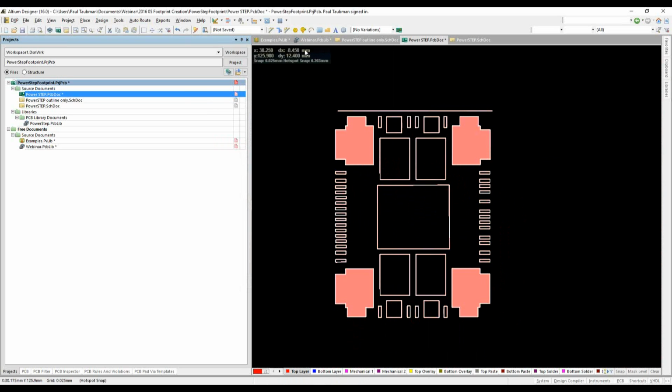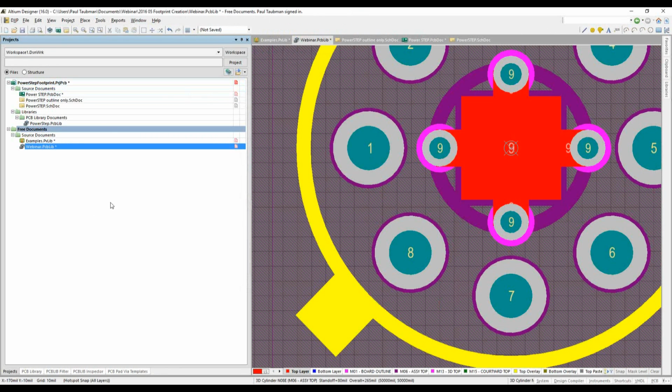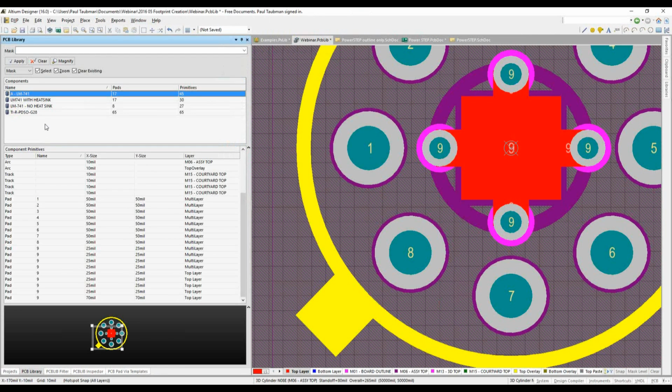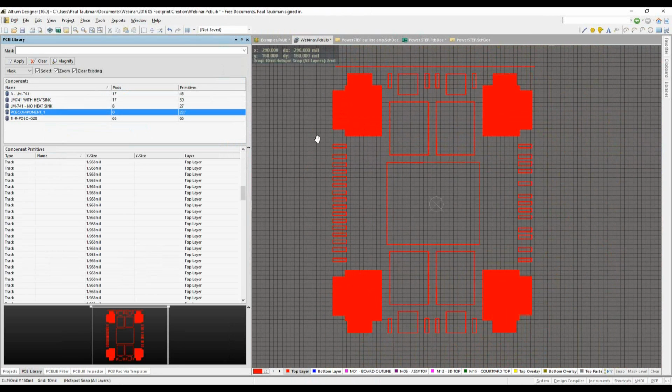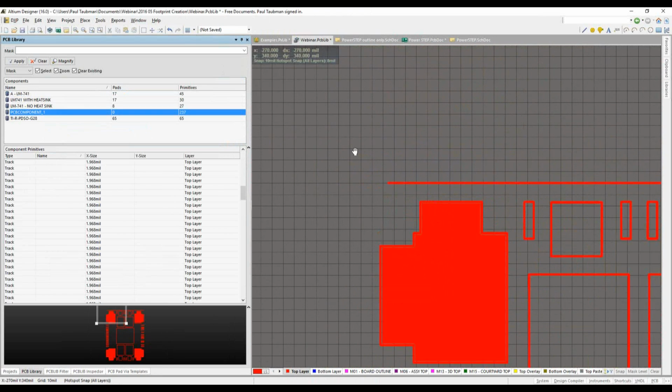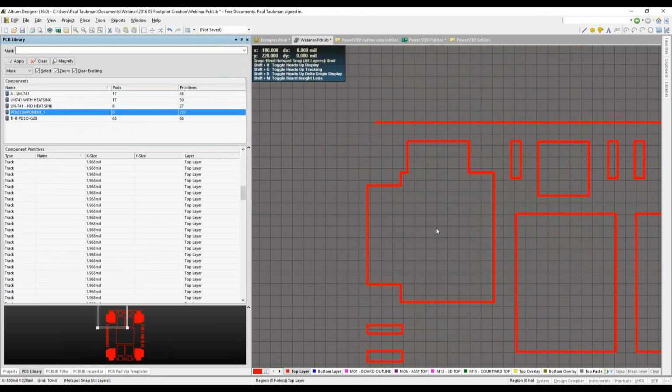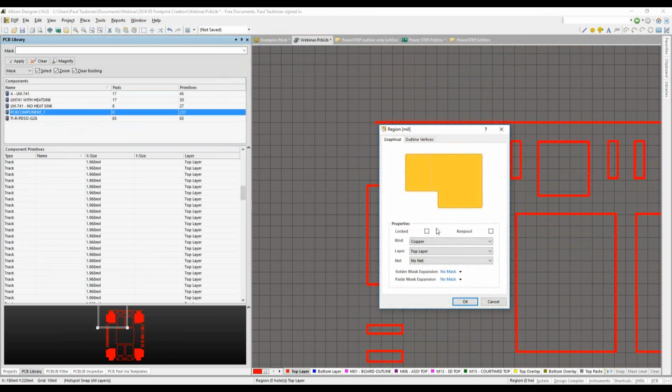And if I bring it over to the PCB library, so let's go over here to my PCB library, I'll create a new part. Okay, so here's my new component, and I do a Control V. All right, and there is my outline. But more importantly, for those things that I had as polygon pours, they get converted. Polygon pours can't be polygon pours in the library because there's no rule definition for it. But they change them into copper regions.